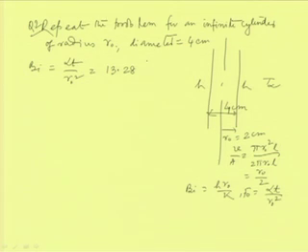I am sorry, this is the Fourier number that is remaining unchanged. Fourier number is equal to alpha t by R naught square, which is 13.28, and 1 by Biot is basically k by h R naught. This is also remaining unchanged because R naught is not changing and other things are constant. This is again the case of a cylinder of aluminum.